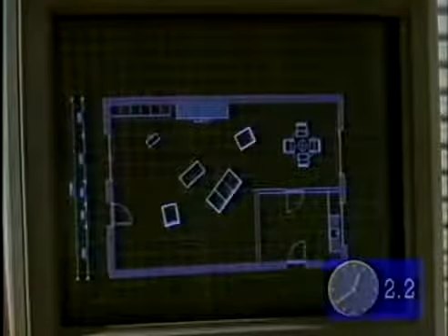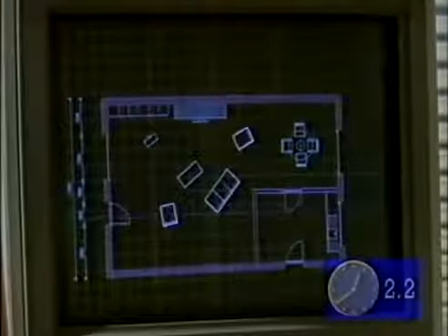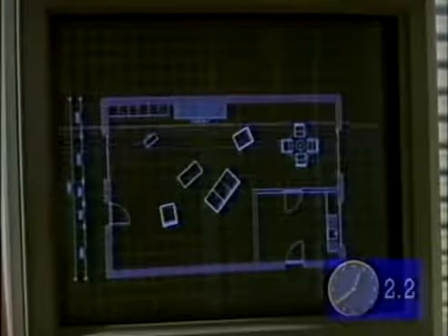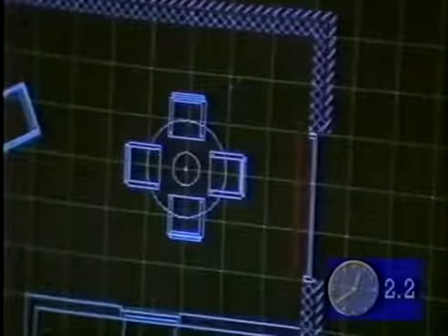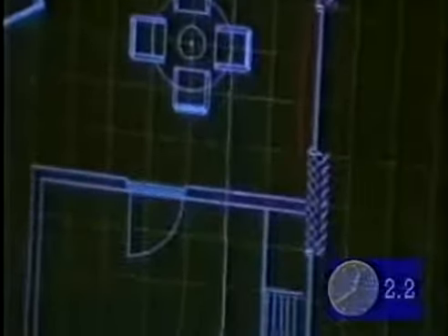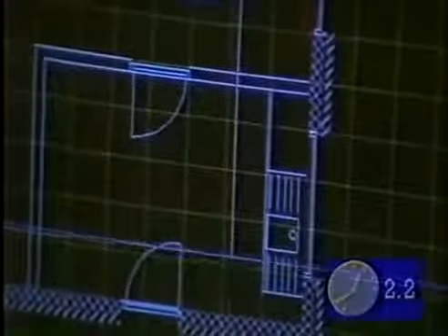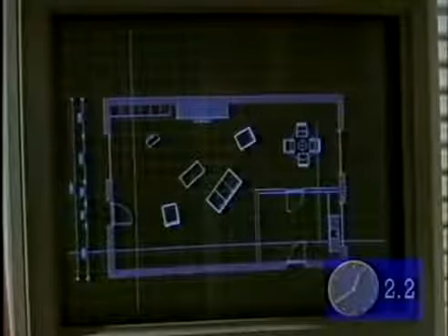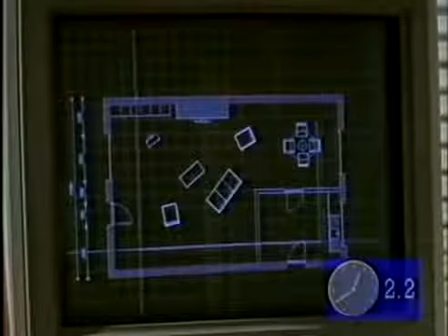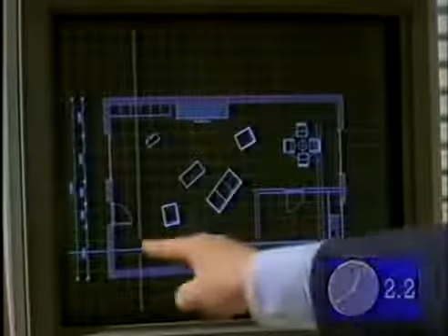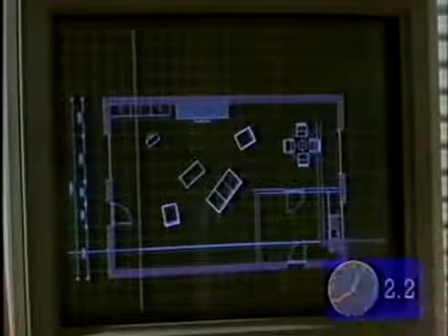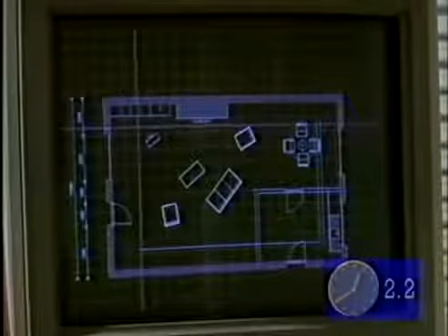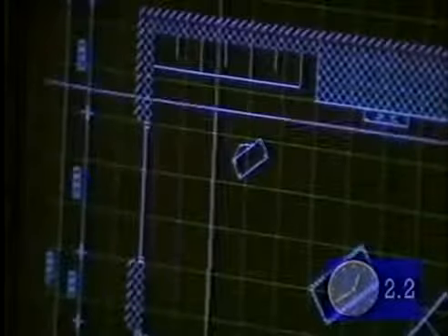I now want to move to a particular location, so let's start up here. I can then issue the J command again, and whenever I go down to there, it is going to generate me a line. I can then go to there, and as I've given it a second angle, it has put in the first parallel line and also mitered the corners automatically. So again, I could come up to here to issue that line.